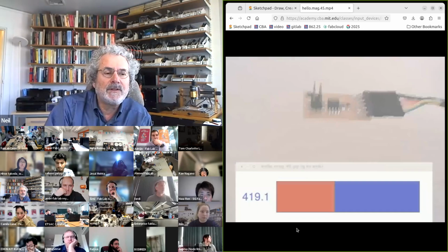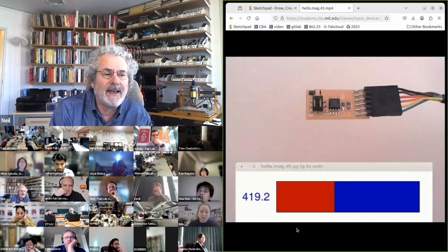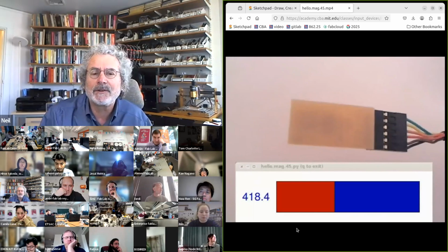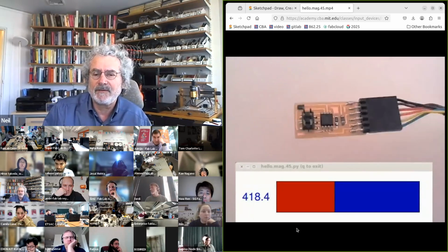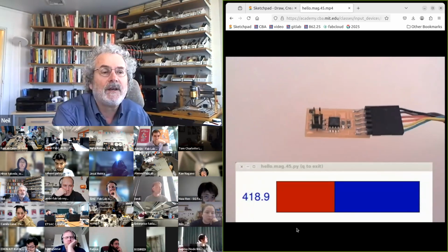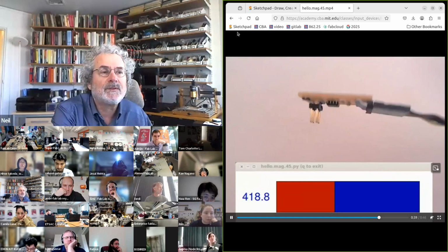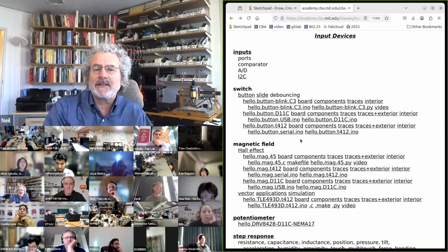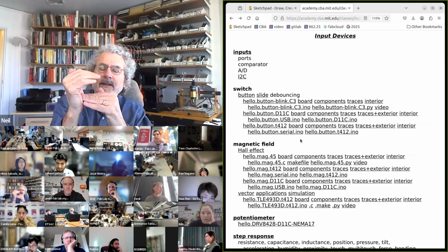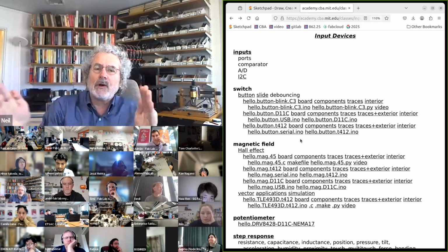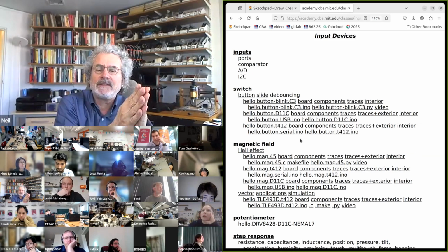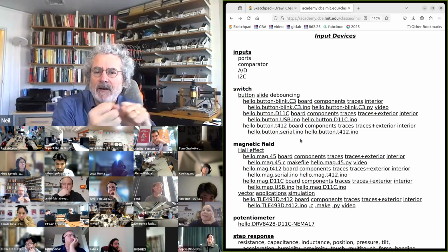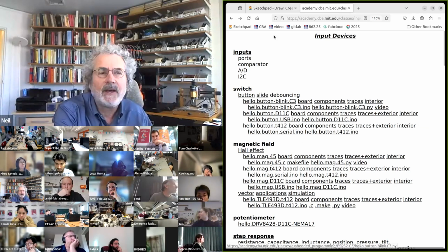And then here I'm going to do it with nothing. And if I flip it, you'll see a small change. And that's actually Earth's magnetic field. So it's sensitive enough to measure Earth's magnetic field. So that's measuring magnetic field. And a killer app for this is if you want to find when a lid is closed or when an axis approaches an end stop. This is a common way to sense proximity of a magnet and a sensor.